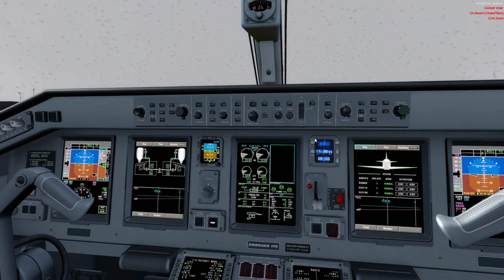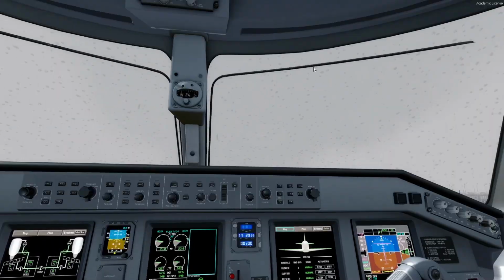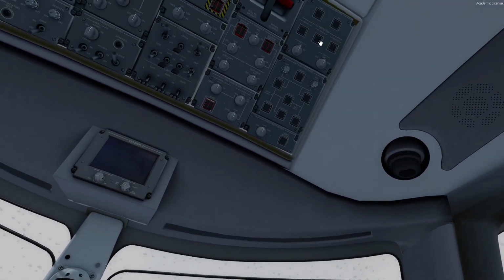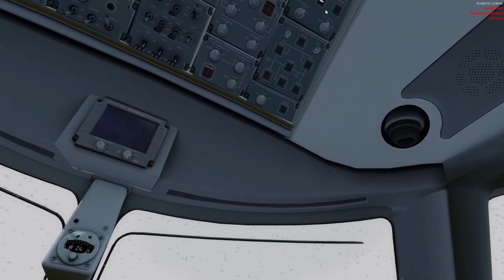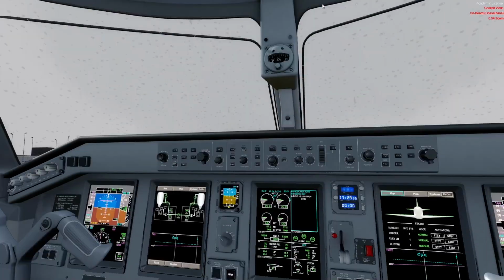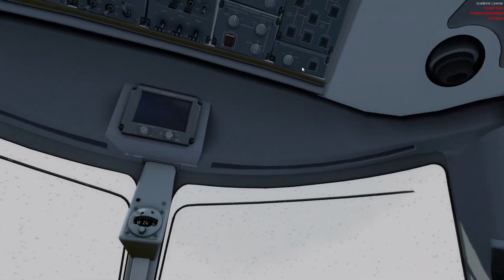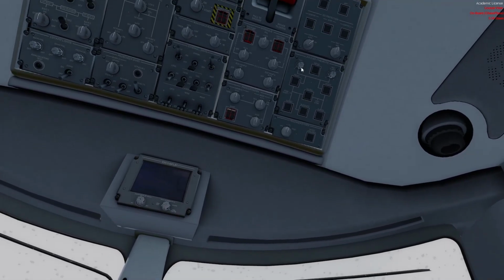So that's pretty much it. Just to summarize: before takeoff, dataset menu with the mode in auto. During flight, ice detectors will make the system work, and after landing, if we need anti-ice, we need to force the system on via the mode selector. You don't have to worry about the wing anti-ice before you turn it on, because remember, it doesn't do anything. Wing anti-ice would not turn on until we are at least 40 knots in the takeoff roll.